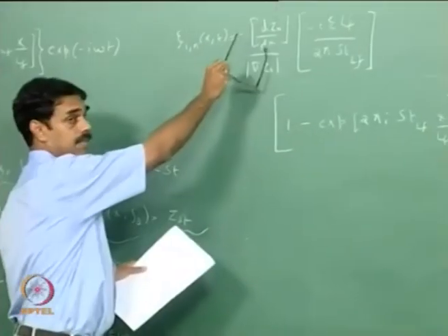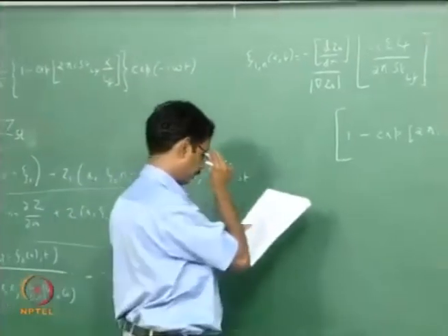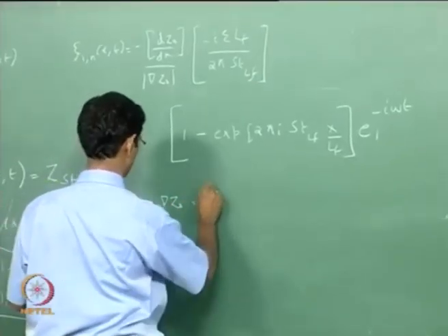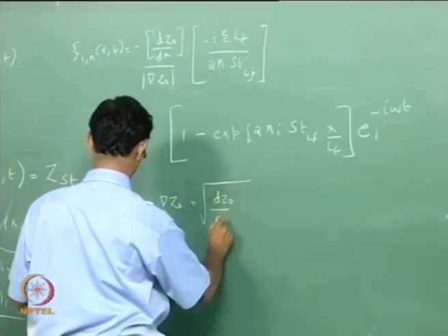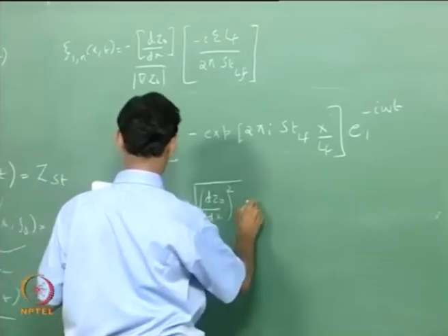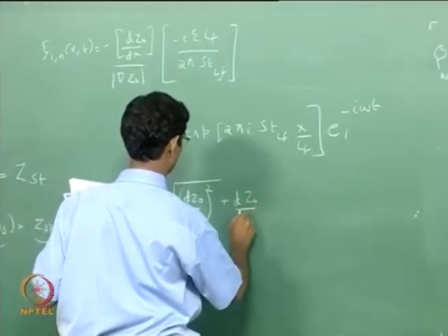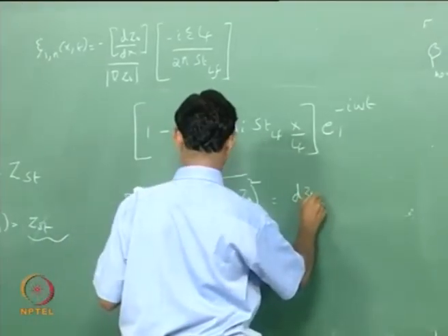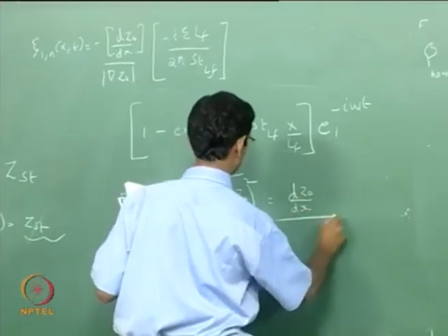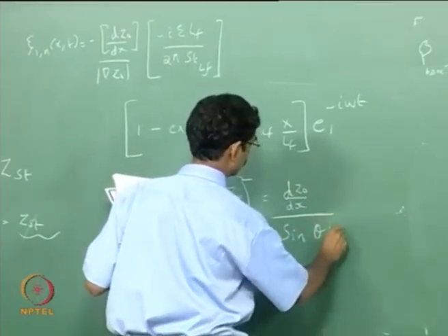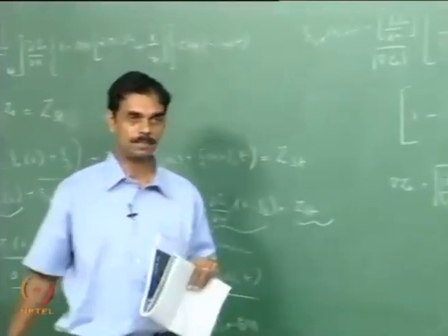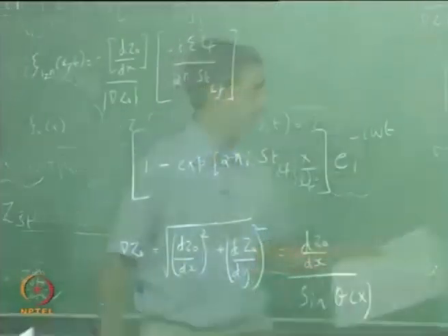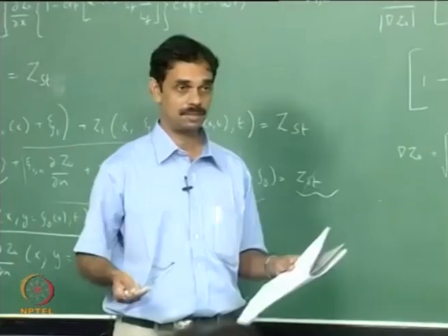Now this term we can write in terms of flame angle. When you talk about flame angle, as opposed to the premix flame where the flame angle was constant, like a tent flame or a conical flame, here as you saw the flame angle was a function of x.